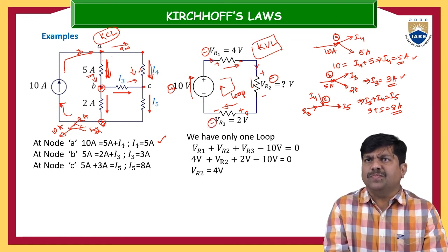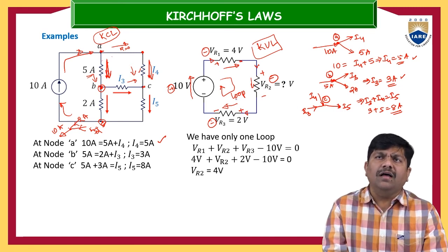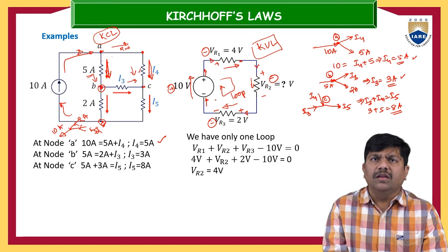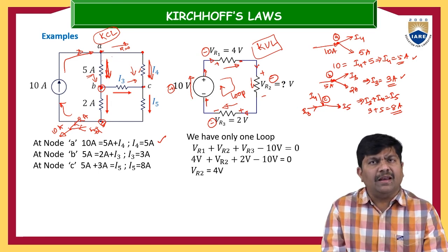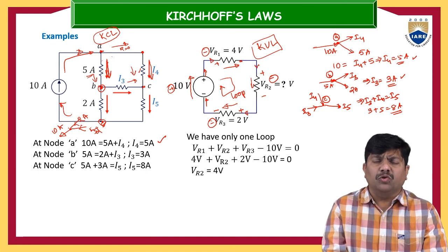See why we have taken plus minus, plus minus, plus minus: because this is one resistor, this is a second resistor, this is a third resistor. It means VR1 is the drop across the R1 resistor, VR2 is the drop across the R2 resistor, and VR3 is the drop across the R3 resistor. All these three resistors are connected in series. Why? Because whenever the current leaves this battery source, from there onwards up to the terminating instant, the current value will not change, because all these three resistors are connected in series. If there is a change in the current value, it may not be a series connection, it is something else. Based on the current magnitude and the configuration in which the elements are connected, that tells us how many in the complex electrical network are connected in series and how many in parallel, and whatever the resultant connection, we will see in the forthcoming videos.